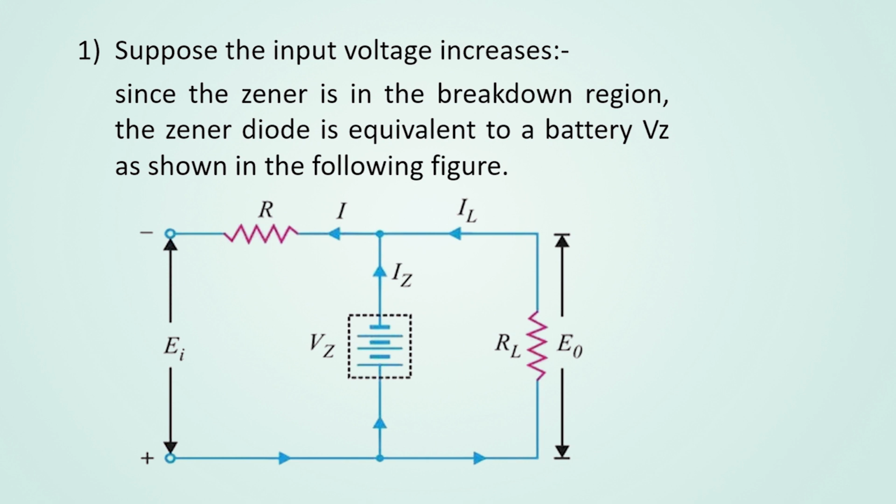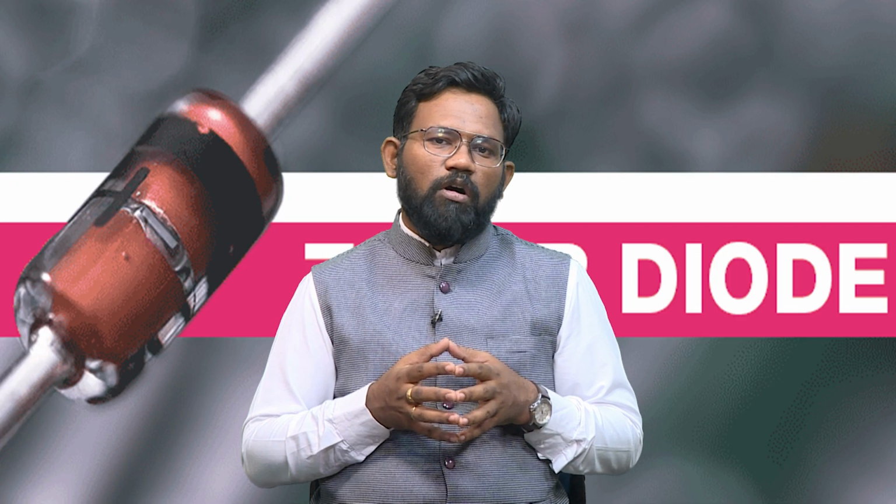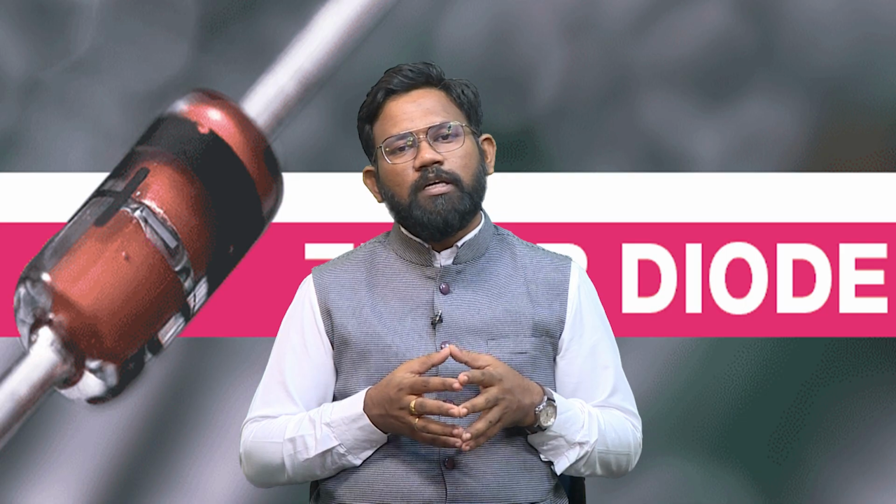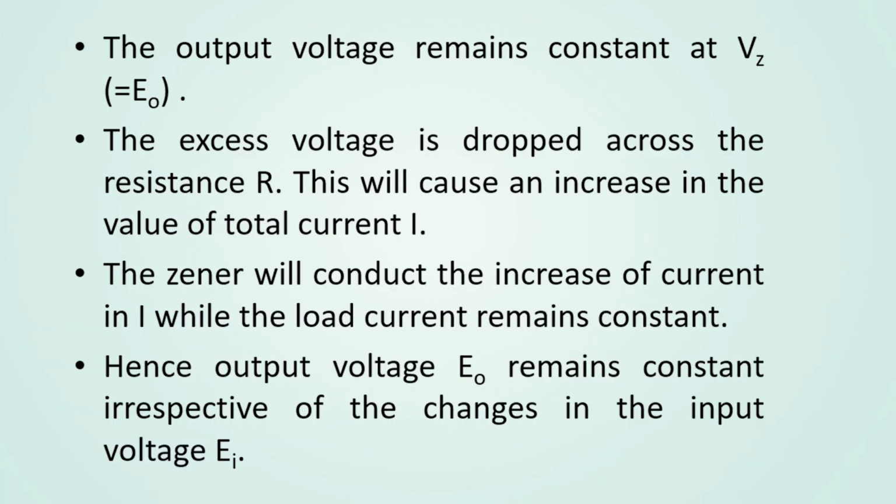So, let us take one condition, that suppose the input voltage increases. Since the Zener is in the breakdown region, the Zener diode is equivalent to a battery Vz. It is shown in the figure that the Zener diode is replaced with a battery source with a voltage Vz, and the current Iz is flowing through it, the load current is IL, the voltage we are getting at the output is E naught, and the input voltage is Ei. So, the output voltage remains constant at Vz equal to E naught.